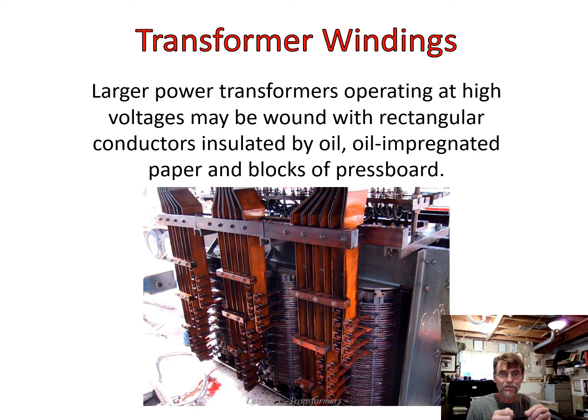Okay, but at some point there's going to be enough voltage to push the current across that air barrier, and that's what we see as a spark. So the same thing is true for any insulation. If the voltage is high enough, it can defeat the insulation and push the current through it. So in our high voltage transformers, we have to work a lot harder to make sure that we have that insulation value. Okay.